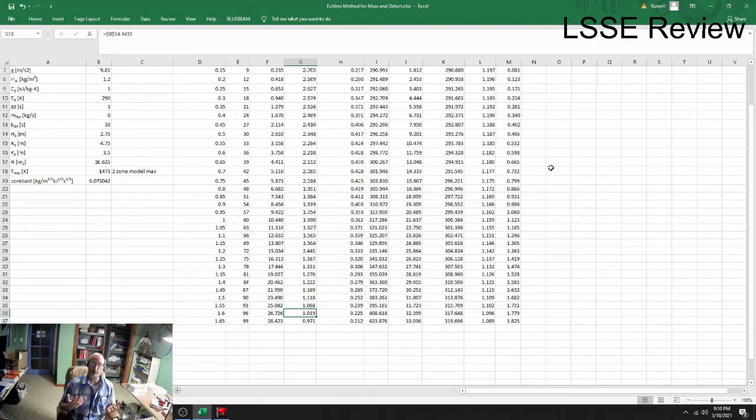You're actually allowed to breathe smoke in, as long as you can prove that you're below a certain carboxyhemoglobin level, so that you are not incapacitated. You prove that, you could be in a smoke environment. You could prove, hey, you're going to have burnout in a room. You just don't have enough combustibles to justify fire spread before flashover. You can go that approach. Or you can go by the approach where you're never going to descend the smoke layer below 6 feet.